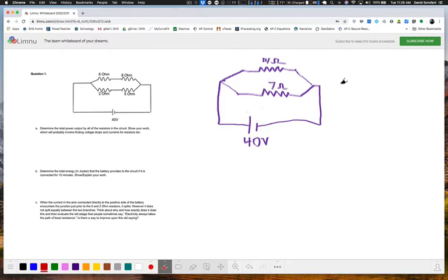And to do that, I'm just going to use Ohm's law. So the current will be the potential difference across each resistor divided by the resistance of that particular resistor. So applying that logic here in this top branch of the circuit, again, there's 40 volts of potential difference, or a voltage drop, across the 14 ohm resistor. So we would just take the 40 volts and divide it by the 14 ohms. And that's our current, 40/14ths of an amp. And we'll label that, I suppose, as I1.